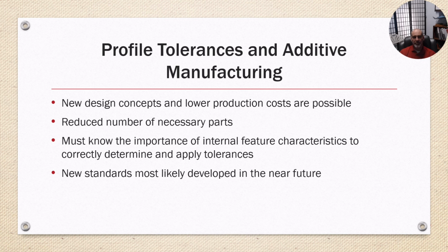You make your thing with that additive manufacturing. It doesn't have a whole lot of flat features on it to measure. They model it, you hold it to a surface profile tolerance, and then you check it on a coordinate measurement machine.